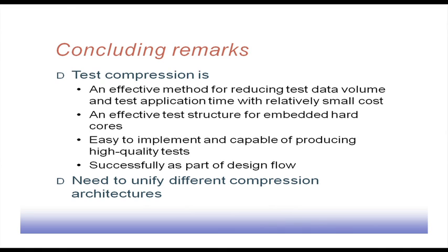At a low frequency we can transfer the pattern set, and then using a decompressor we can decompress the test patterns and apply them to the circuit. We can also do response compaction. By response compaction we can combine the responses into one or two signatures, and that way the amount of information to be stored for the response will also be less.